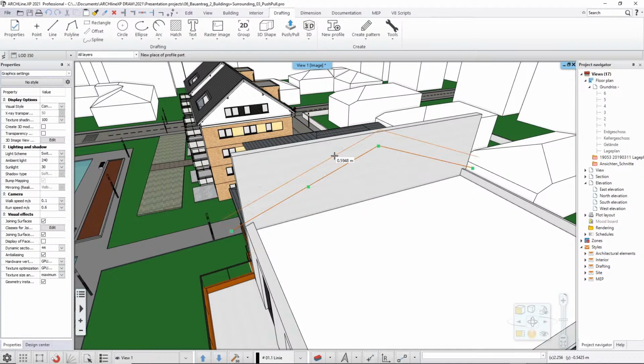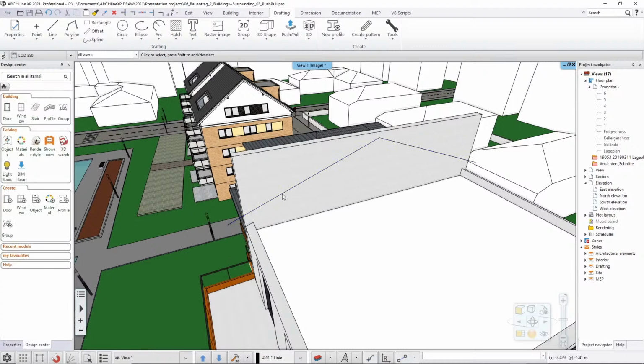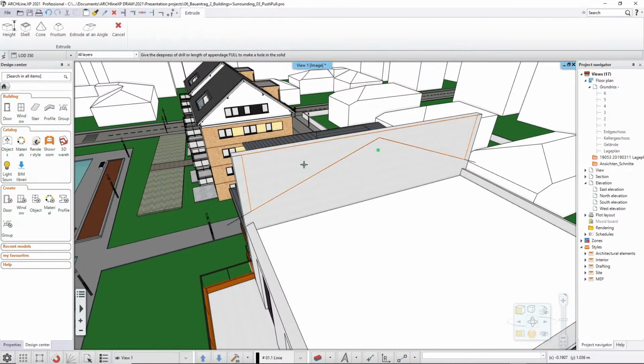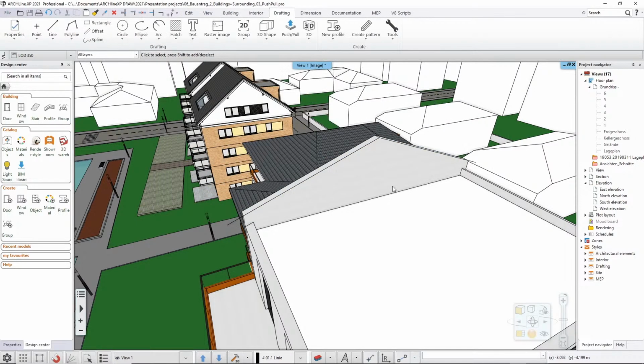And with this one, I can change its position either below this line or above this line, and I can use a value. Now in this case, I will use a value of 0.3 meters, like that. And then this will be the new position. And then I will also use the Pushpull tool now above this area, somewhere around here. And then I will just pull it back towards that direction. And when it's long enough, I just click once, and then it will make it disappear.